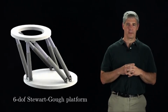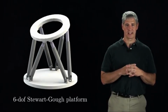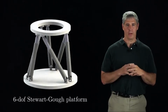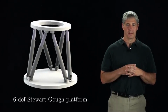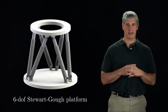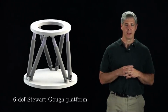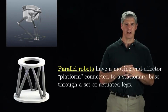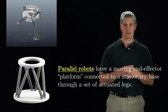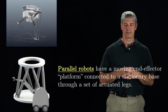The final example is the Stewart platform, which moves with the full 6 degrees of freedom of a rigid body. Each of the 6 legs is actuated by a prismatic joint. At one end of each leg is a spherical joint, while the other end has a spherical or universal joint. The Stewart platform is popular for applications like aircraft simulators, since it can move the virtual cockpit with all 6 degrees of freedom. The Delta robot and the Stewart platform are examples of parallel robots. A parallel robot is a specific type of closed chain which consists of a moving platform attached to a base through a set of actuated legs. For the rest of this video, I'll focus on parallel robots.